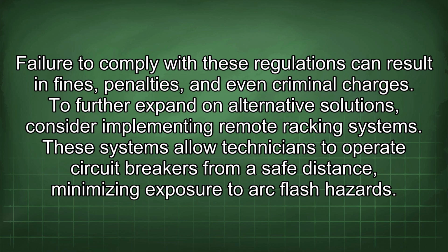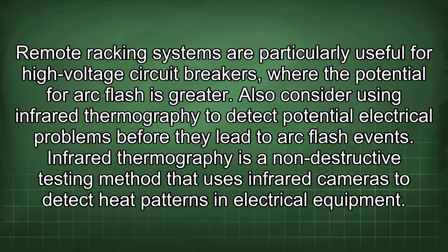To further expand on alternative solutions, consider implementing remote racking systems. These systems allow technicians to operate circuit breakers from a safe distance, minimizing exposure to arc flash hazard. Remote racking systems are particularly useful for high-voltage circuit breakers, where the potential for arc flash is greater.